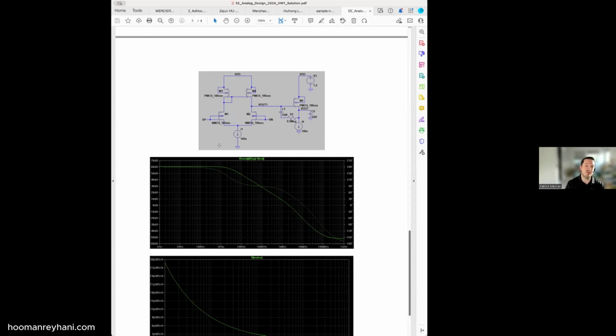Another thing that one could explore is doing a current reuse architecture where you have both NMOS and PMOS inputs. That complicates the biasing a little bit. Of course, if you then add cascodes on this, that requires a lot of headroom for all of your transistors. But remember, the benefit of being in subthreshold is that your transistors only require about 100 millivolts over them. And so you can actually stack quite a few transistors here, even with a relatively low supply voltage.